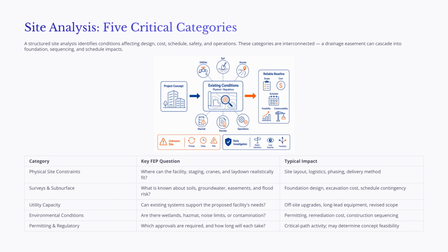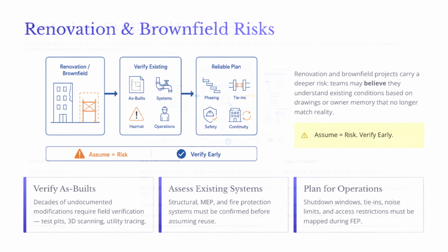A drainage easement may affect building placement. Building placement may affect foundation design. Foundation design may affect excavation duration, and excavation duration may affect the schedule baseline. Site analysis is therefore an integrated planning activity, not a collection of separate studies.